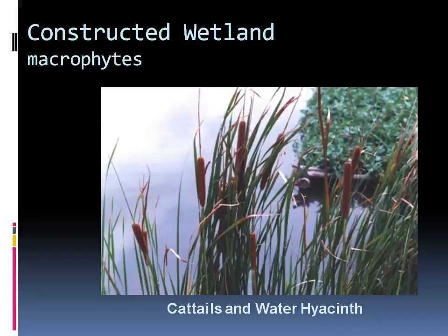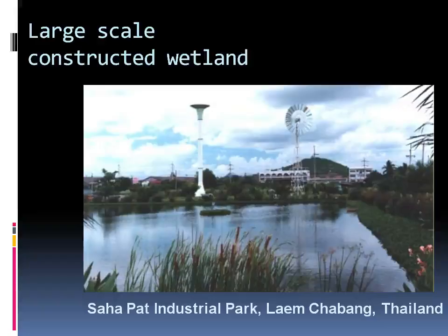Here, in the trickling filter system, the waste is passed through a trickling filter where long pipes rotate slowly over a bed of stones, dripping waste onto an artificial food chain comprising bacteria, fungi, protozoans, snails, and insects. The organic compounds are consumed by bacteria and fungi, which are fed upon by the protozoans, which in turn are consumed by snails and insects.